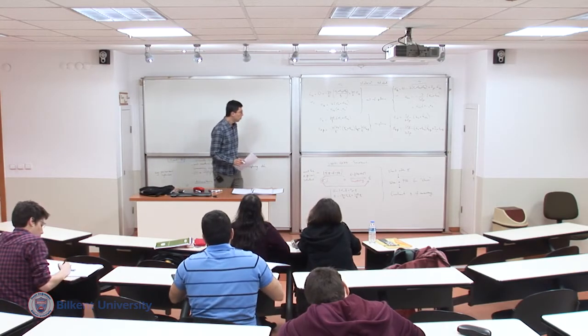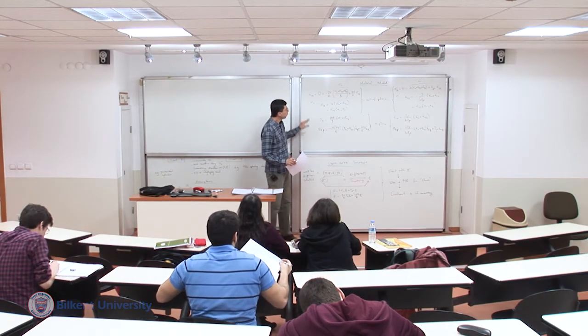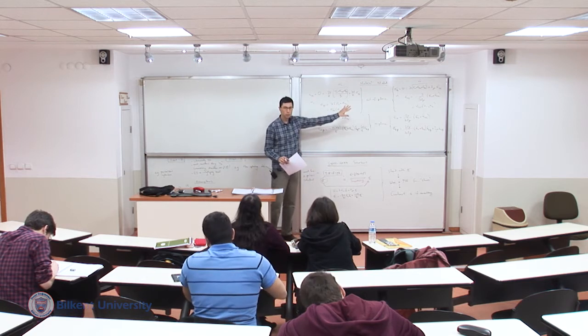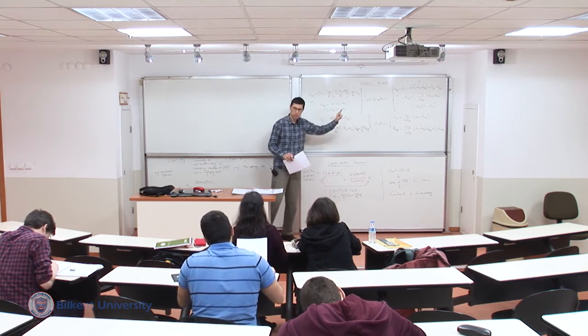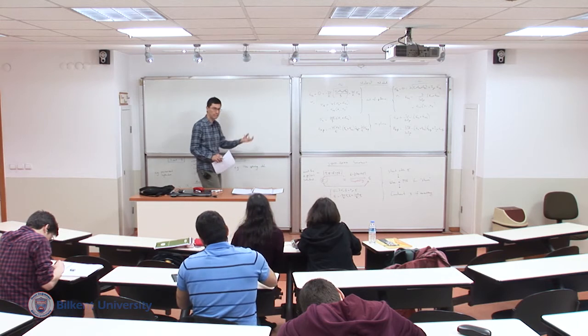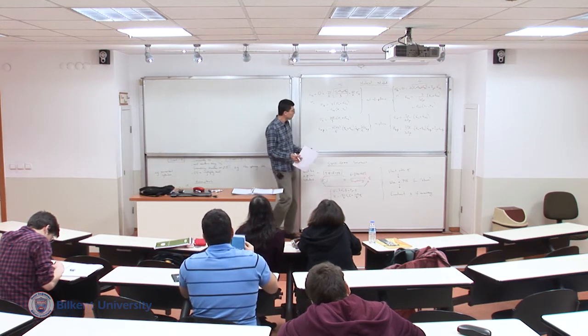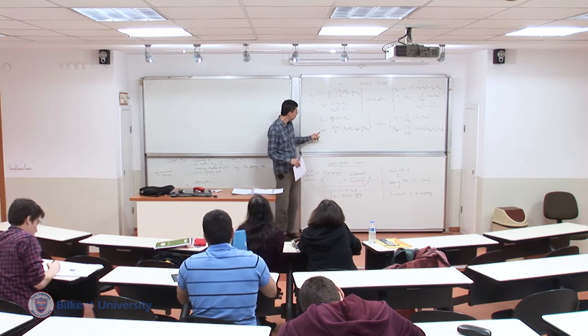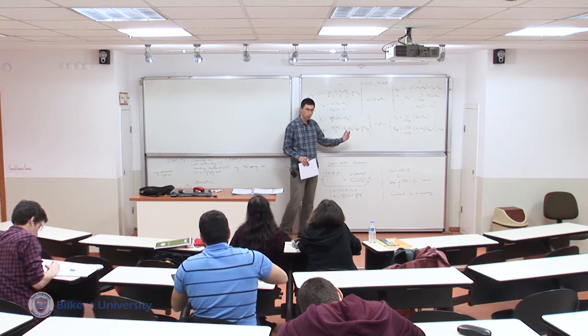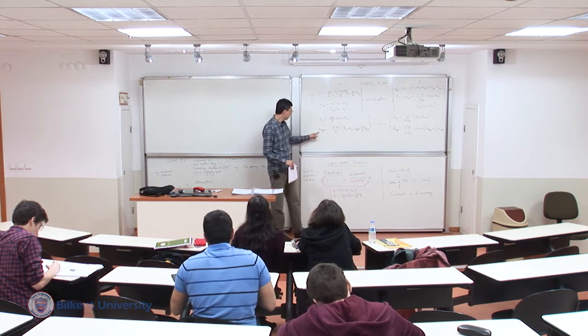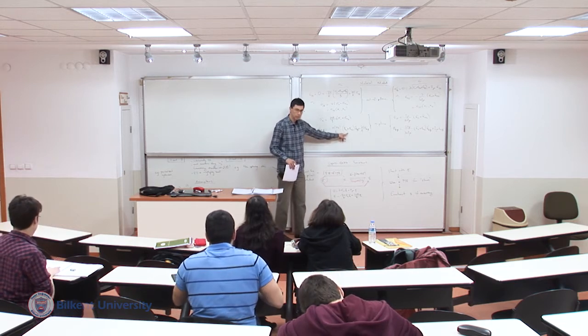Okay, so remember, the goal is to show that eventually both intrinsic problems, plane strain and plane stress, can be cast in an identical framework. So if I want to cast things in an identical framework, I better be able to express the relation between strain and stress in also an identical manner. So this is a relation that gives strain in terms of stress.